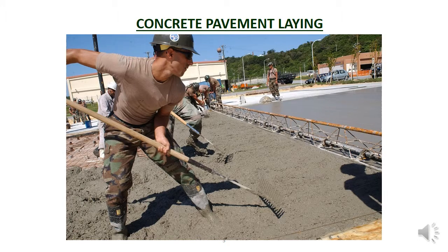This photo shows a concrete road under construction using mainly manual labour. The concrete is being spread by hand, which is what the workers with rakes are doing. In front of them is a screed sitting on wooden forms at each side of the road. The formwork contains the sides of the concrete, while the tops of the formwork are set at the level of the road.